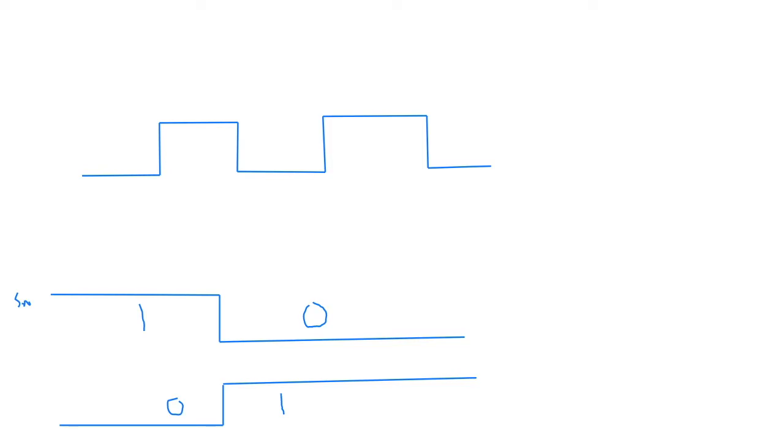Now, when we are triggering the interrupts, we can have different options to trigger the interrupt. One, when it's moving from 0 to up, we call this the rising edge. Or when it moves from a 1 to 0, we call this a falling edge. Or we can say when it is in a stable state low, or when it is a stable state high.